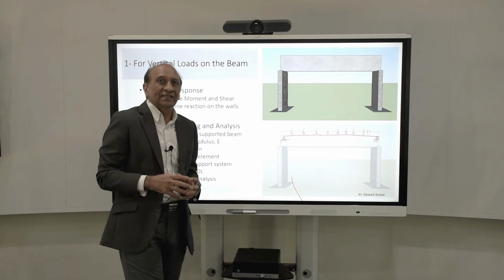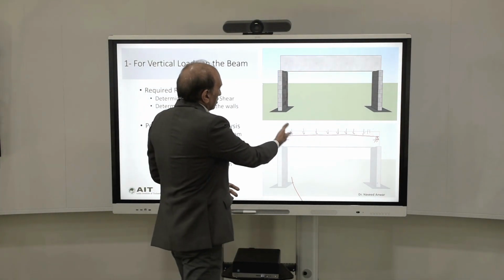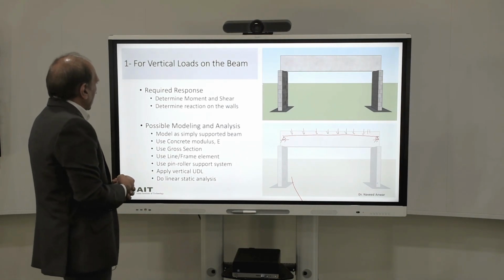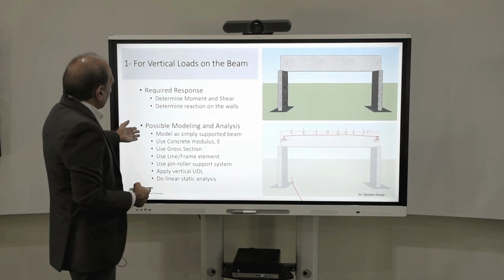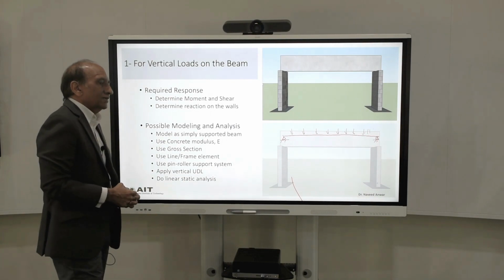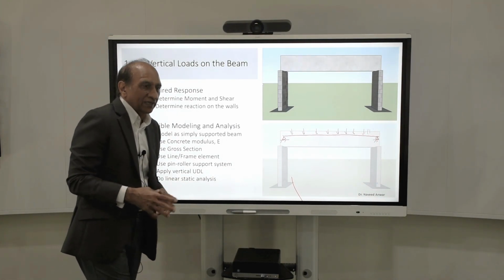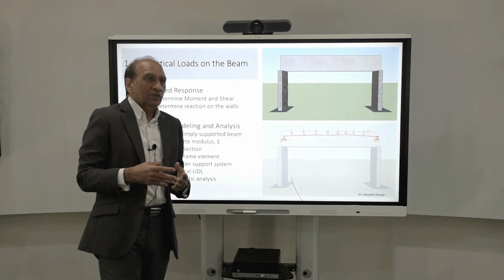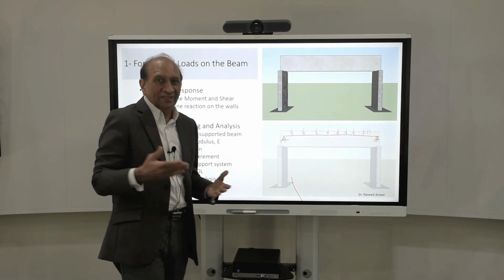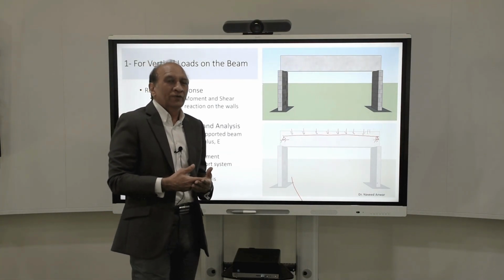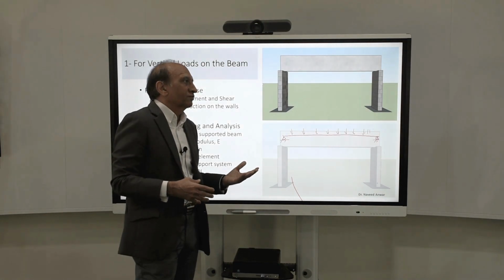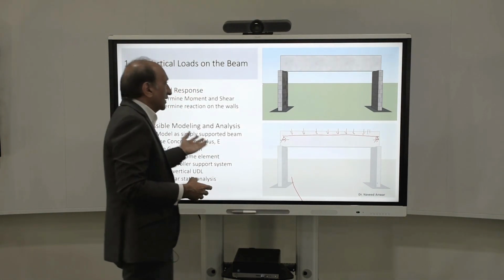But okay, let's forget that for a minute, and we can do this model and we can get the response for the vertical load. So we use the concrete modulus of elasticity. We use average models. We neglect the rebars. We just assume it's concrete. And do we use the initial elastic model or tangent elastic model, or do we use the secant elastic model? There are many options there. So we have to make a choice on which elastic model we will use even at this point.